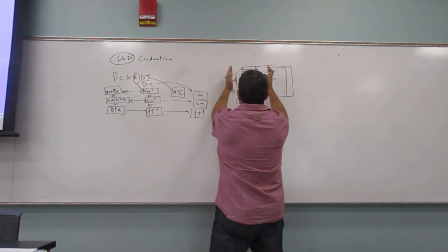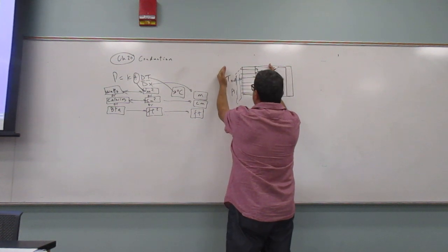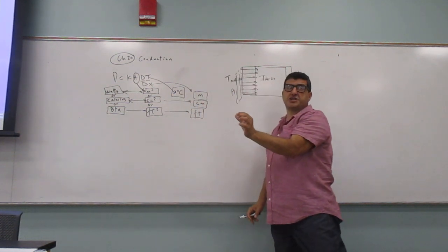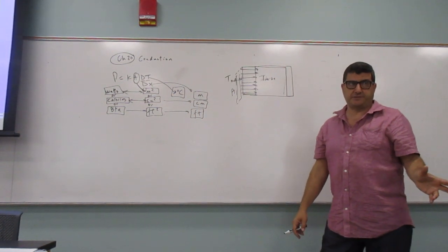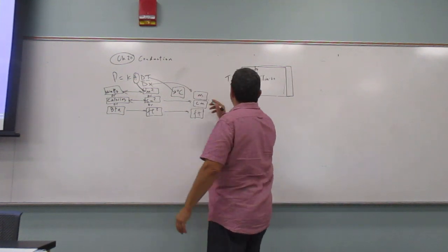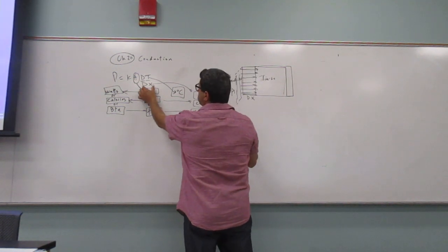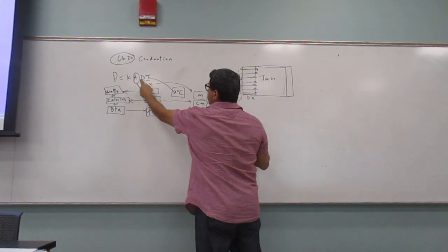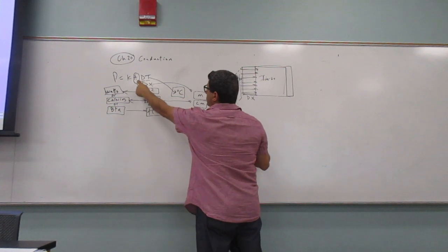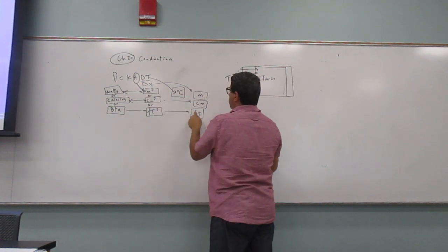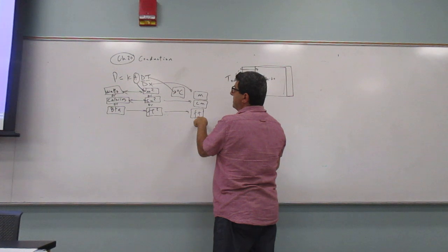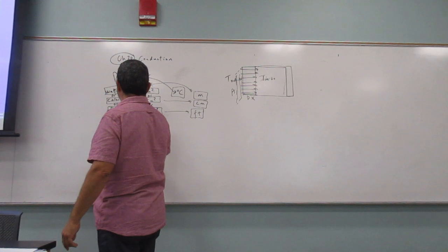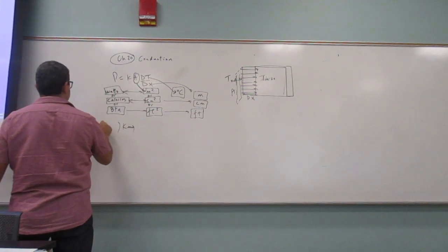Change in temperature is the temperature gradient between the outside and the inside. Because it's a change in temperature, it could be Celsius or Kelvin. And then delta X is the thickness of the material. So if A was in meter squared, then this would be meter. If this one was centimeter squared, this would be centimeter. And then it could also be feet. So depending on that, you have 3 different units for the K. K is the heat conductivity.